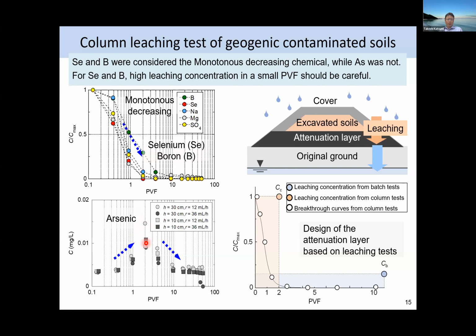Yes, and sometimes we have the leaching concentration values from a batch test, which might be utilized for the design. Okay, so we have to make sure of the behavior of the leaching values, depending on the types of elements and the types of soils or rocks.